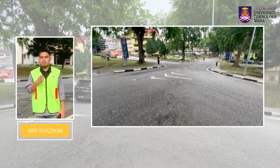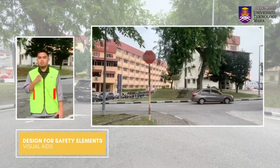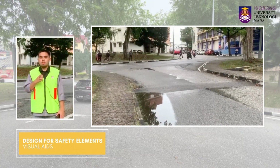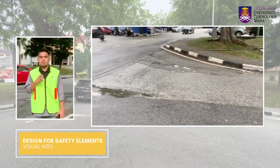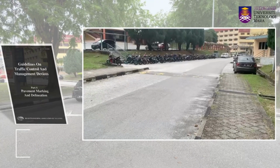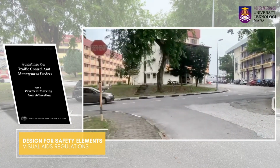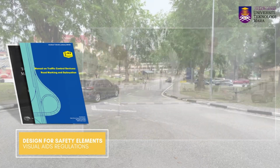As for visual aids, the road markings, yield lines and bumper lines are significantly faded. The stopping signs have also been blocked by trees. This may be hard for the drivers to see. All of this can cause hazardous and dangerous situations for pedestrians and drivers that can lead to incoordination while using the road. To address this, several corrective actions are recommended based on RIM GL 8/2004 Part 4 Guidelines of Traffic Control and Management Device and Arahan Teknik Jalan 2A until 2D.